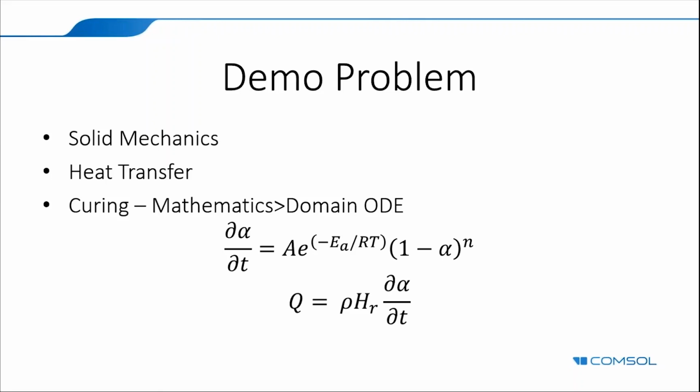But here, this is a kind of material evolution equation that's just at the point, based on the current situation at that point. So you don't get any special derivative for this particular equation. I mean, you could add the PDE interface here and set all the terms, like the mass terms and the stiffness terms, to 0. But why would you do that, right? You're basically building up a whole matrix of zeros that you're not going to need, and it will be inefficient. So it's more a matter of efficiency than accuracy here, actually. Okay.